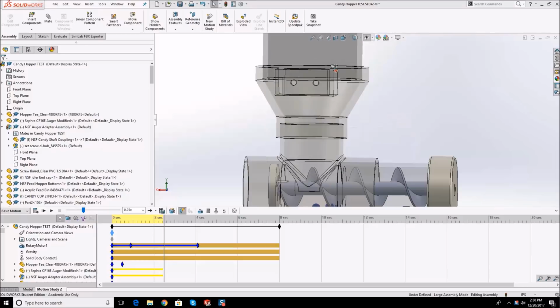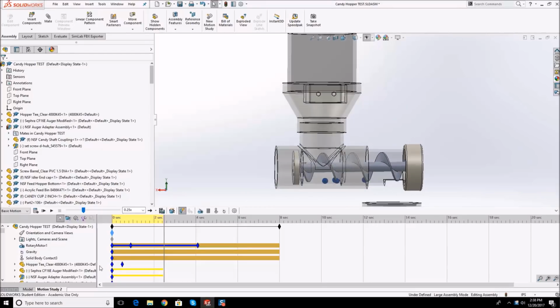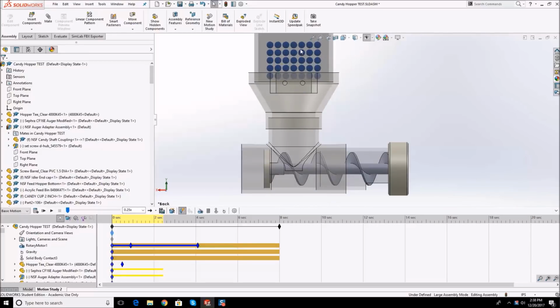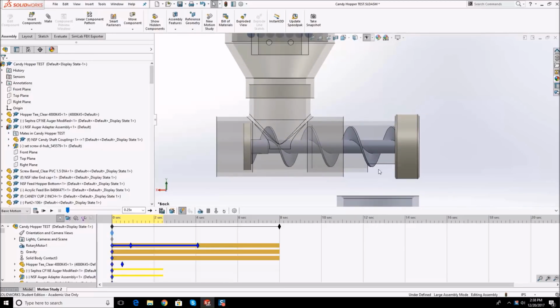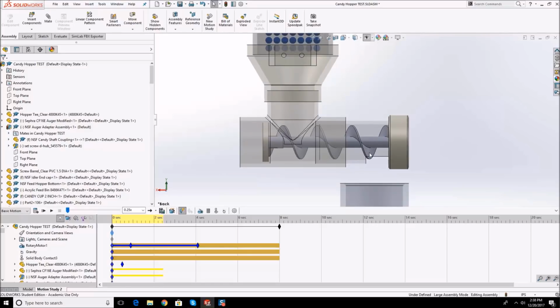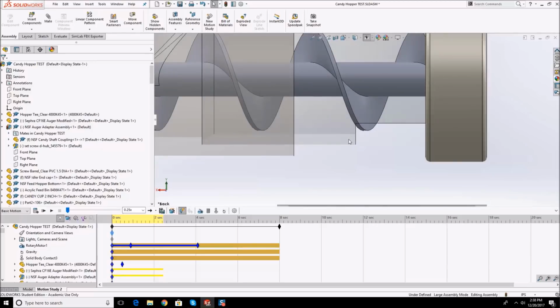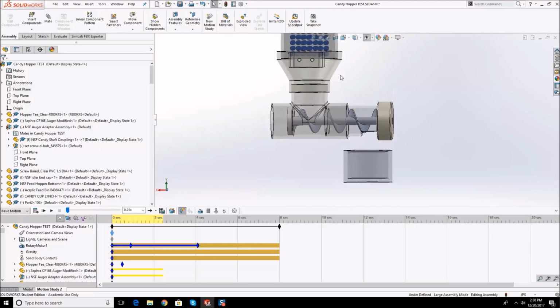So this is what I'm thinking. If I increase the gravity to, say, 300 inch per second, what happens is all the balls come crashing down on top of this and bung this up, and then you have this. The algorithm just doesn't know what to do. What happens if I let the gravity be very, very low is once it gets down to here, it doesn't clear out of this slot quickly enough. So what do I need to do? I need to make the gravity lower, and I need to make the speed of this slow, and then maybe I need to open that opening up a little bit. You kind of have to help it out.